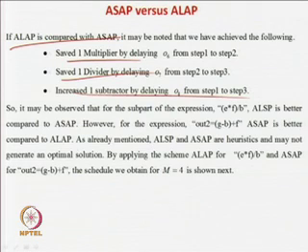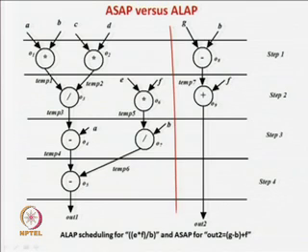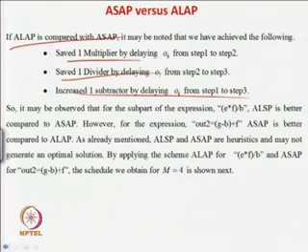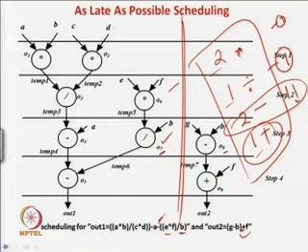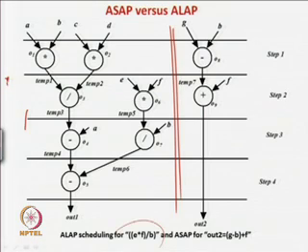Now, what we are going to do, whatever is written over here, let us try to separate this. You see that multipliers and dividers are already incurred for this part of the problem. If you see the two subparts, out 1 and out 2, out 1 is involved with adders, multipliers and dividers, but out 2 is involved with subtractors and adders. So we saw that the subtraction requirement was increased when we went for as late as possible, and for divider and multiplier we got better solutions when we went for the as late as possible algorithm.